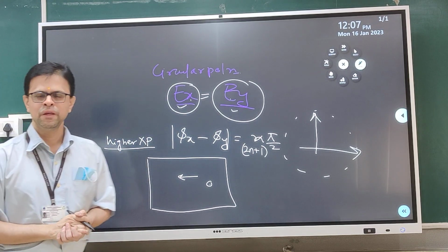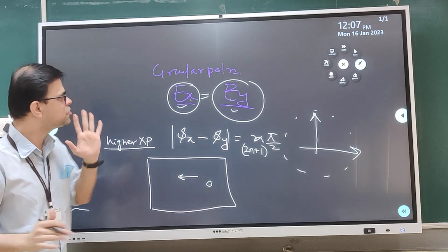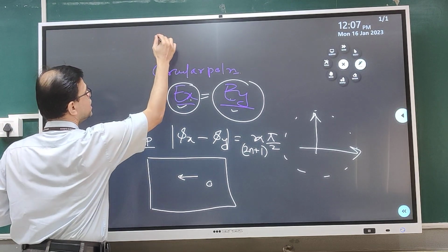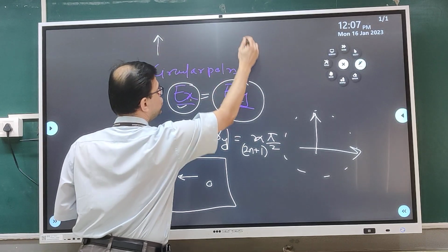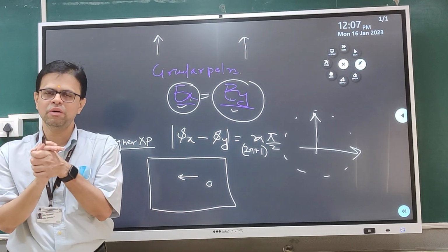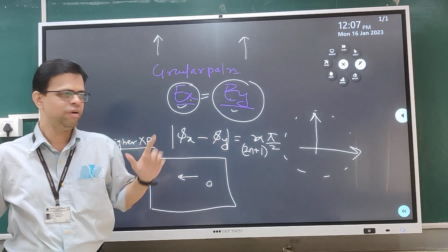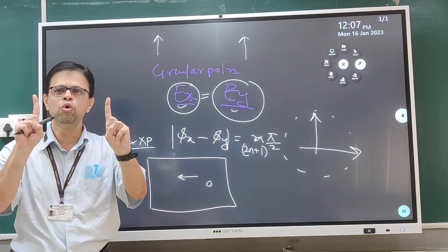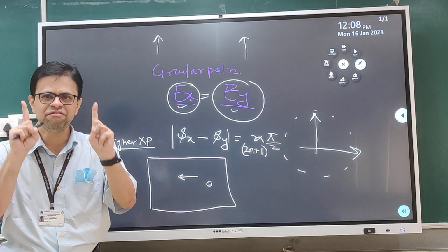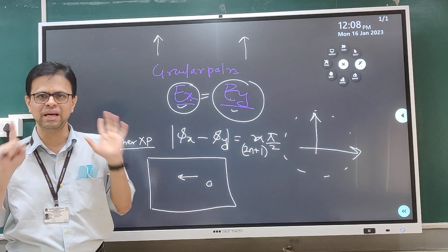radiation pattern. Now what exactly does a cross polar measurement tell you? I'll just try to explain that. When in the radiation pattern you do a copolar measurement, what are we doing? When we are doing a copolar measurement, the two E planes are matched in their phi and theta direction.